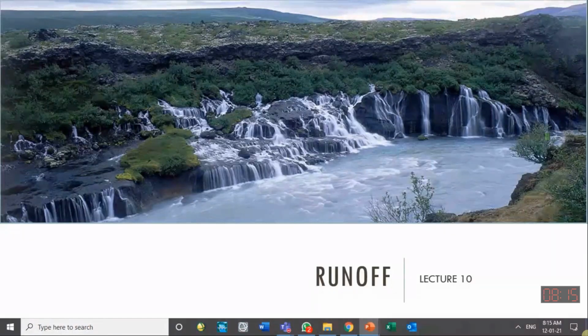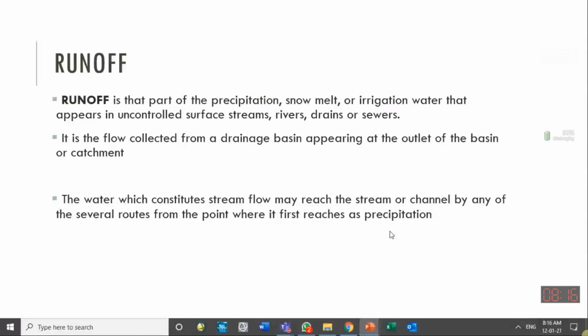And we introduced to you, if you are using a current meter, what is the method to find the total discharge in a channel. We have to divide it into small vertical sections, small strips, and then measure the velocity using the current meter in each strip, multiplying it with the flow area. We get the discharge of that strip. The total sum of all the discharges gives us the discharge of the whole stream. Similarly, other methods were introduced to you.